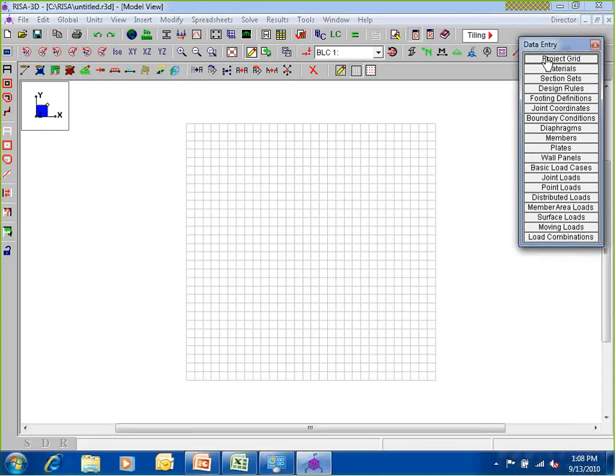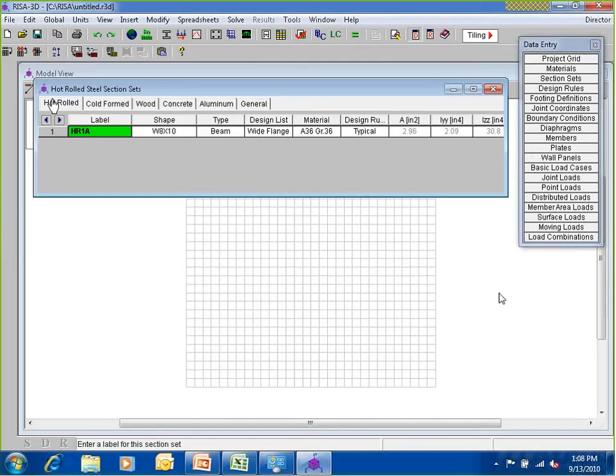We're going to start by setting up our section sets, as I mentioned. Section sets are a way to really start your model and use the same type of member throughout a certain area. For example, we're going to be putting horizontal members in our tank element, and that's going to be called an arc member. We want to make sure that they're all the same and similar, so that when we go to resize that arc member, we end up resizing them all the same way.